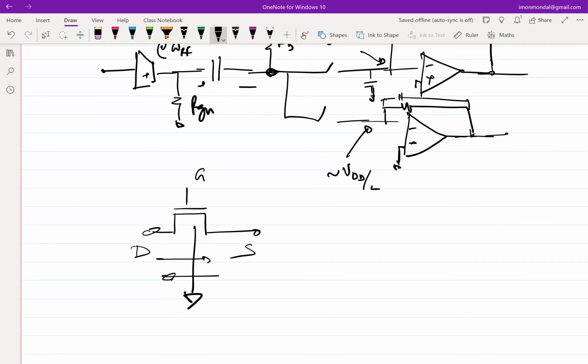So this also gives you an idea why PMOS is a problem, because these voltages will never go negative if you are using the LNA that we have talked about in the class. Right? If you recall, these voltages can never go negative, right? Because if the voltage goes negative, then the transistors will go out of saturation, right? In principle, it cannot go, but even if it goes, it will not work. But it can go above VDD, right?